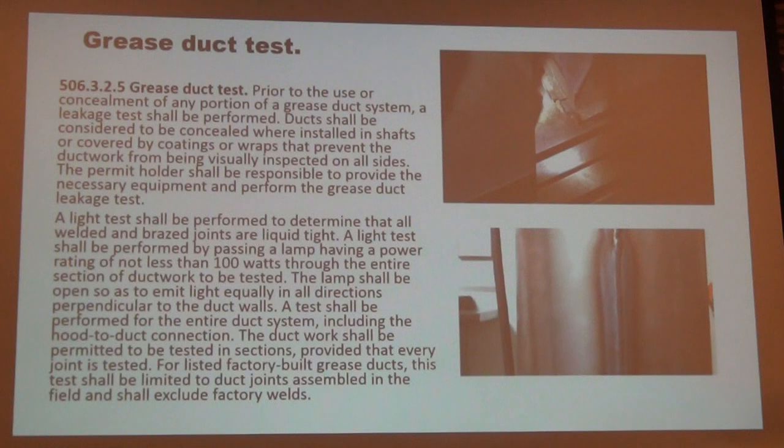I had one at Beaumont Hospital, and the ductwork was up on the roof, and it was a sunny day. So how am I gonna light test that? It was a big duct, so I told him to put some cardboard down, and I'll crawl through the ductwork, and if I see any sunlight coming through. It was a reverse light test. It worked, if it's big enough. It was a job done by Limbaugh. What if you would've got stuck?